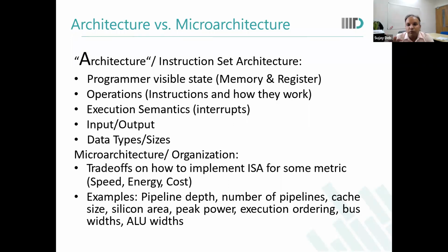Now, how complicated do you want to make your switch? For example, whether the switch will be pipelined. If it is pipelined, how many stages it should have. Will it have some intelligence? For example, do you allow adaptive routing? How do you maintain quality of service? If there is some high priority message that needs to be delivered, do you have the capability to deliver it separately, or assign priority to certain messages? How do you maintain flow control? For example, how far can this switch see downstream?